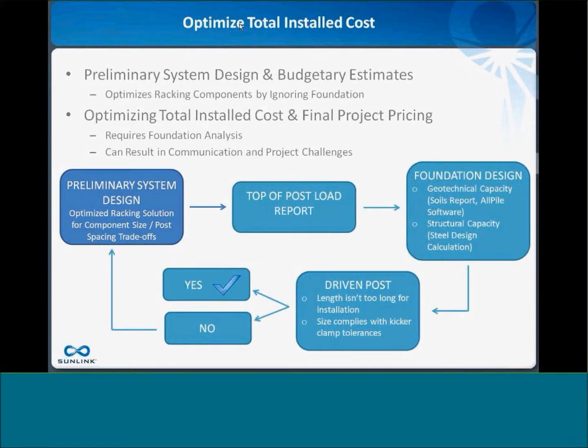But until you have a final foundation design, whether that's through a geotechnical report where you have design parameters given by your geotechnical engineer, or if you're going to do push and pull tests, after you've finalized all of that testing and you've confirmed that your post is within the size length that you can allow for with your installation patterns, and that your total installed cost is minimized with that foundation design, you really can't confirm your project specs until you have all of that together.